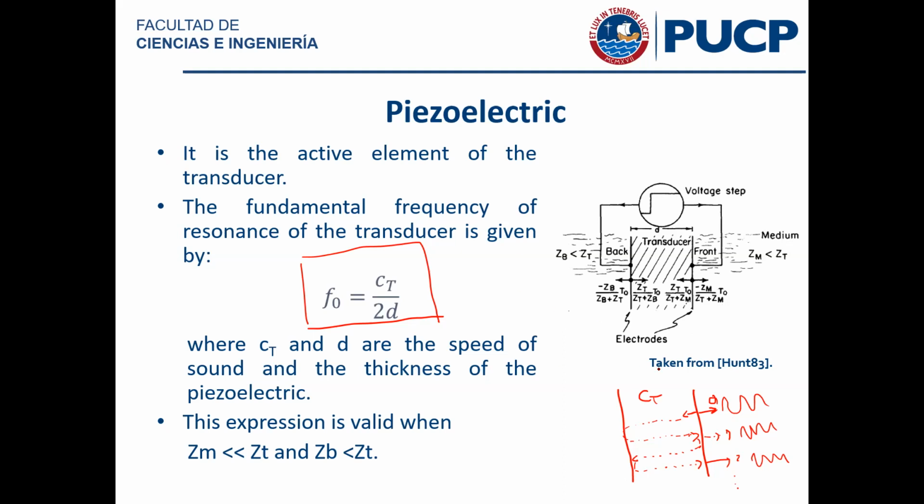That is, you need the phase that's accumulated going all the way to the end and then coming back to be equal to 1 period of the oscillating frequency, right? Because if it's equal to 1 period, then you know that all of those multiple reflections are going to be in phase, and they are going to make the output signal resonate. That is, each one of the new reflections that comes is going to add to the total power that is transmitted. Okay?